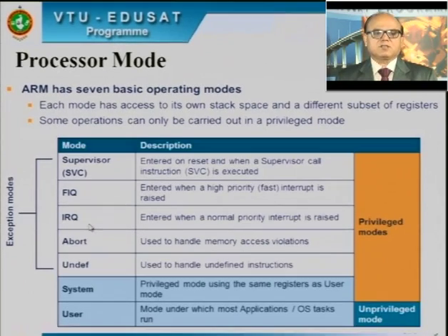Coming to the interrupt request mode, IRQ mode, the ARM enters this mode of execution when a normal priority interrupt is raised. A device or an instruction state of execution may raise an interrupt and request the execution of the interrupt handler code.